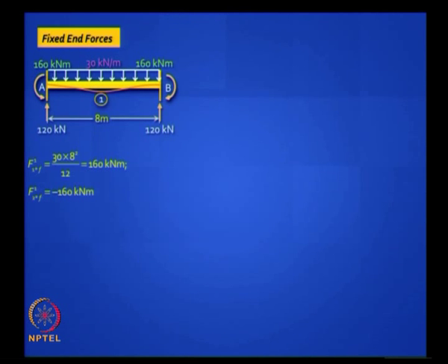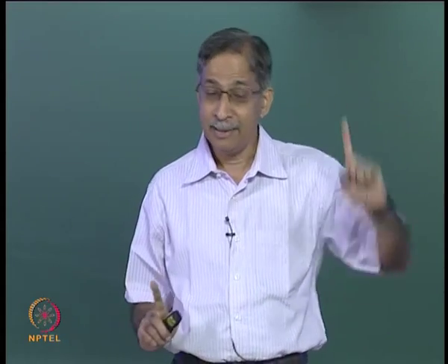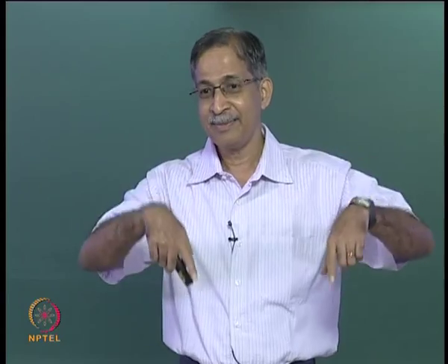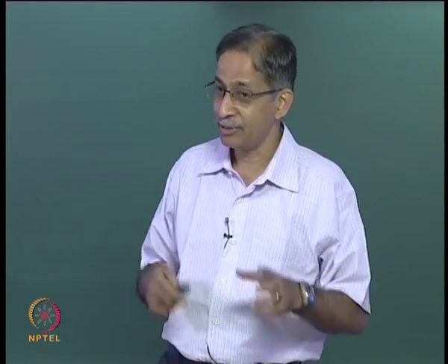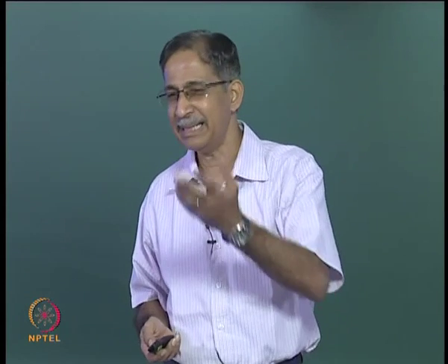Now we have to find the fixed end forces. We've done this problem earlier, so can I go fast over this? You can work out the fixed end forces. Remember, you also need to find the vertical reactions. Why do we need to do that? Not only the fixed end moments, also the vertical reactions, because in the global coordinate they pile on to those vertical forces in the coordinates you've identified.